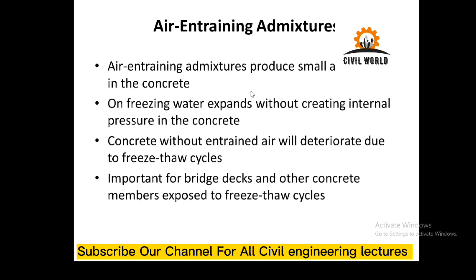Because of these cracks, once a thawing cycle comes, more water seeps into the concrete, which freezes once the temperature goes below 0 degrees centigrade. Again, additional pressure is exerted, which increases the crack width and thus leads to deterioration of the